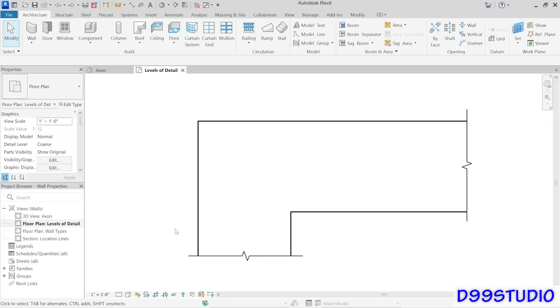come together. And the thing, of course, that you'll notice is that these walls are only showing their thickness, the outermost thickness of the walls, and none of the internal construction. Now, these are brick walls that have a masonry backup and insulation and so on. And so there's a variety of different layers of material in these walls, but we're not seeing any of that in the current view. So this is the first thing I wanted to talk about, levels of detail.